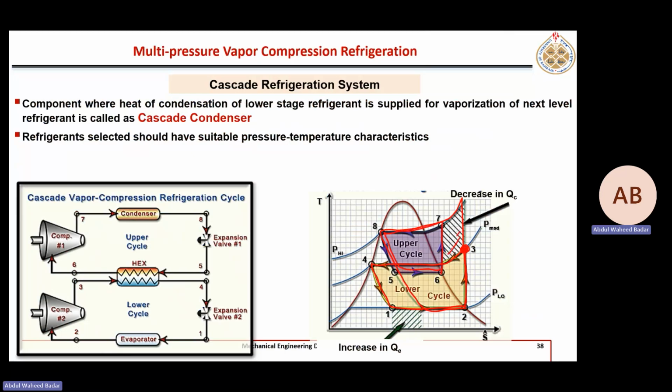So this is a decrease in condenser work, condenser heat, and in the single fluid, this 0.8 will end up here after throttling. But now it is here and then this, so there is an increase in refrigeration effect when we are using two fluids instead of one single.